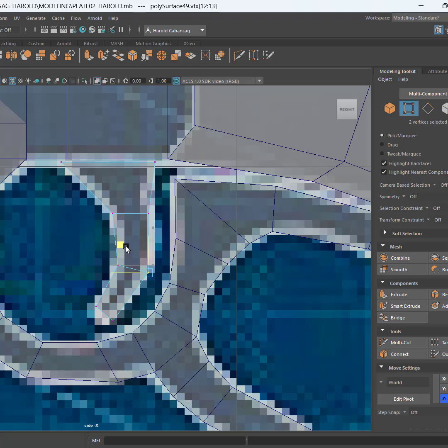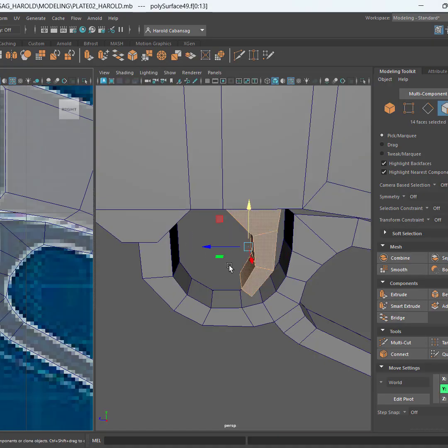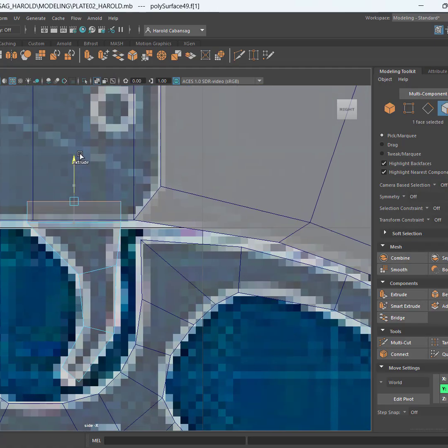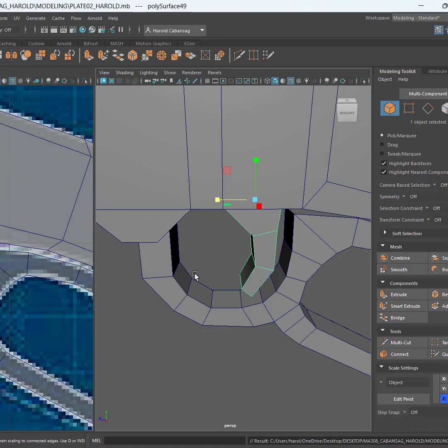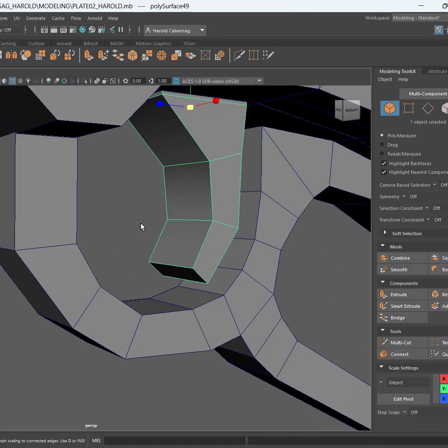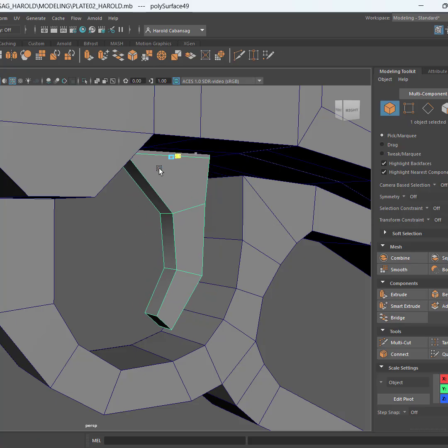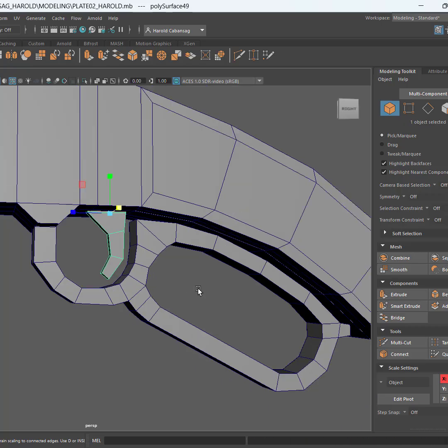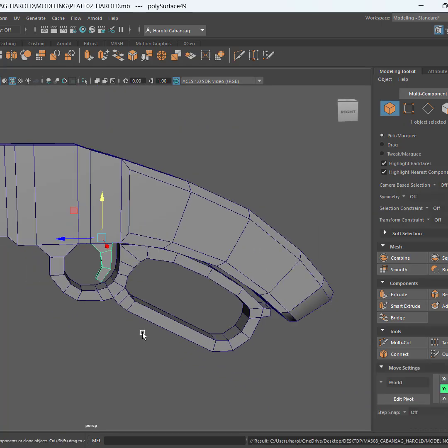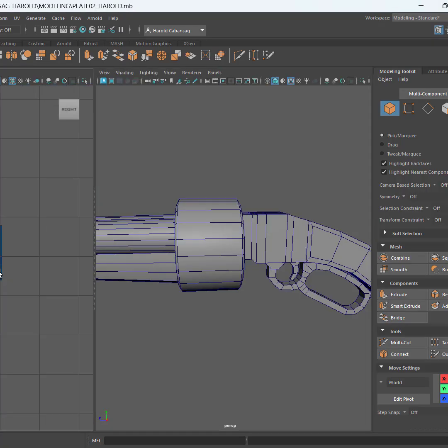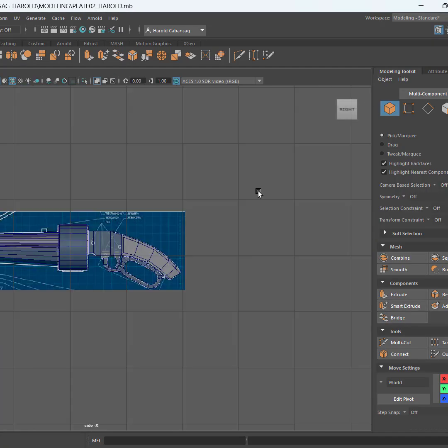And then I'm just sliding this a bit so that the curve can be achieved, and then I can select the top of that polygon, and I can shift once more and start dragging there, saving the work, and then I can press R and scale it, thin it a bit there, so that now all of my moving parts or my mechanical parts so far are modeled.